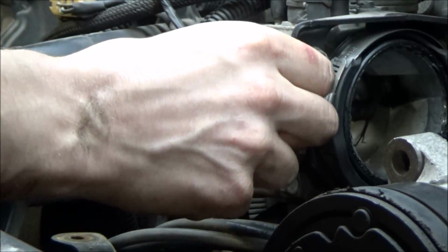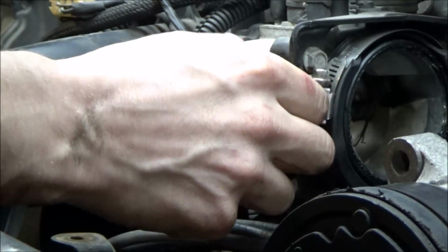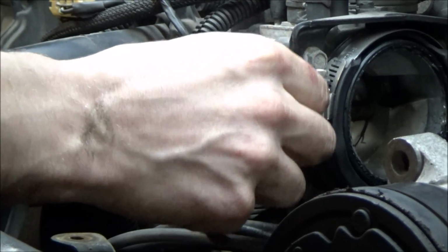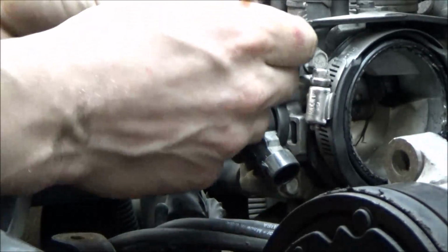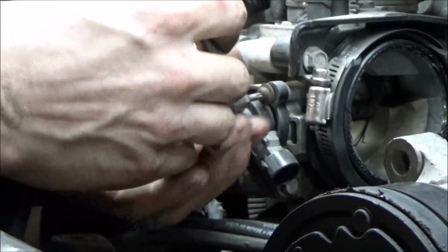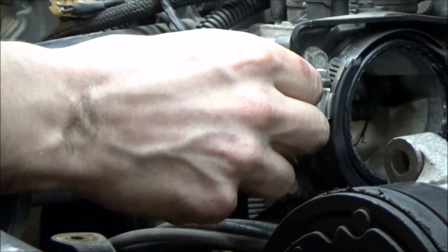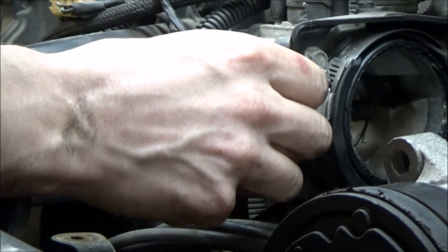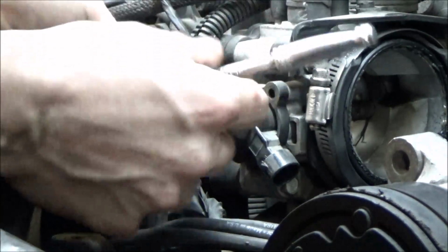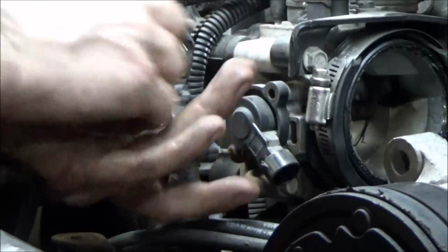But something you got to watch out for on some of these units, these throttle position sensors need to be adjusted to have the proper voltage reading with a closed throttle. I don't believe that this design is one of them. I don't see any slots or anything like that for rotating the sensor when I was looking at the new one. So I don't believe that's what we're looking at here, guys. I think this is just a plug and play sort of unit. So that's good. That makes changing these out a real breeze. Nothing really else to think about.